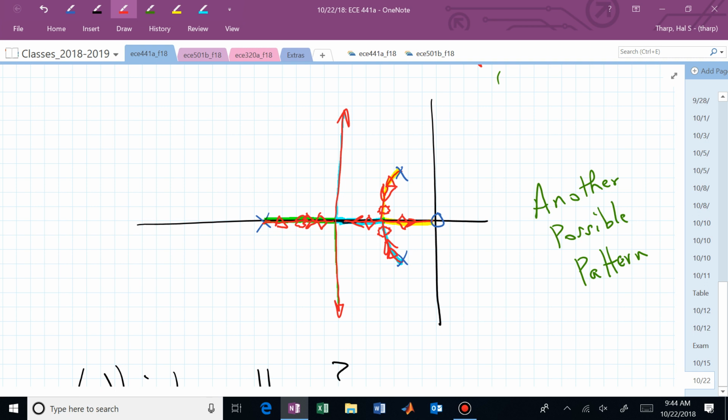Let's say k equals 6. Now these 2 diamonds that are going towards each other have met and separated, and this one is getting close to that 0. So as I adjust k, these crazy shapes are moving symmetrically around this root locus diagram.